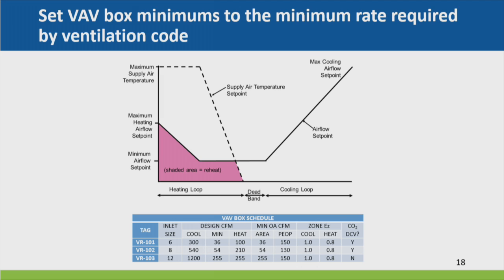How many people have air handlers that serve what we call zone groups, which are like you can serve part of the building but not the whole building, right? That's been in the code since 1991, often overlooked. But if you have a system that's bigger than 25,000 square feet, you have to break it into groups of zones that have different schedules or have the capability of different schedules. Well, when you do that, the airflow you need for ventilation is going to go down when only one of those zone groups is occupied and all the rest are closed.